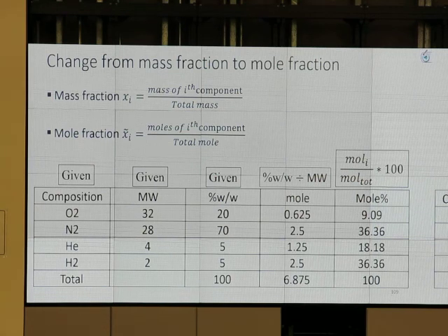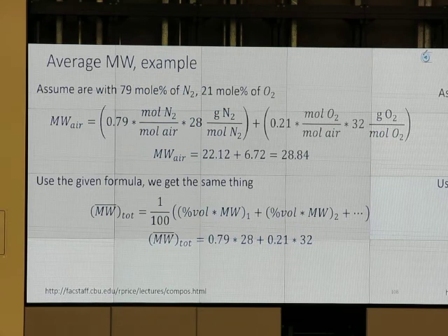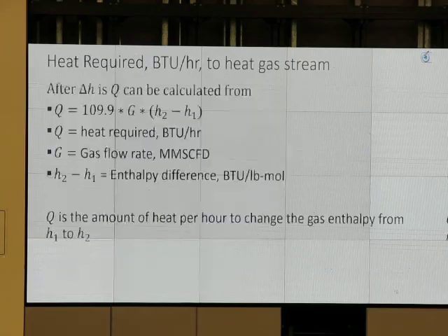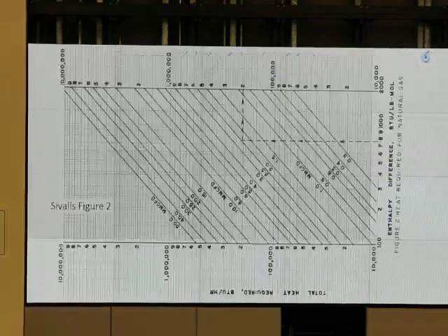The average molecular weight. After we get the average molecular weight, we divide it by 29, or you can do 28.8 something or 28.9, so that we know the specific gravity. If we don't know the specific gravity, we cannot do several things. Look at this one,